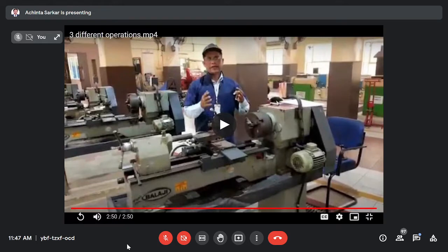Again, that is to be sent to the manufacturing department or the forming department. They will do some rework to maintain the accuracy again, and those dimensions should come under the drawing size and within the tolerance limit that has been given to them. So it is not that if it says to maintain 45 degrees, and it is 44 degrees and some minutes, it will not be acceptable; it is acceptable if it is coming under that tolerance range.